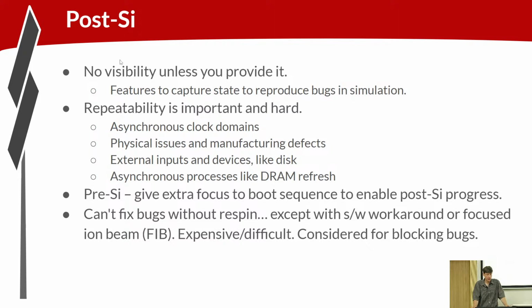In order to enable post-silicon work, there should be a very clear focus pre-silicon on making sure that the functionality of your hardware is stable enough to at least get out of the boot sequence. Sort of secondarily, to make sure, well, first that you can reset the silicon reliably, then that you can boot the silicon reliably, whatever the boot process is.